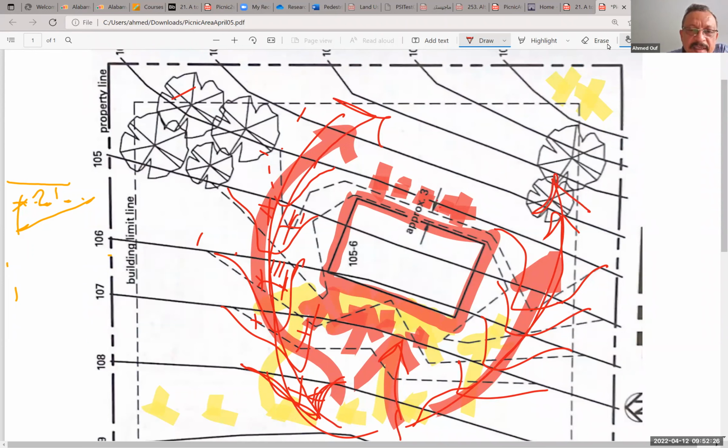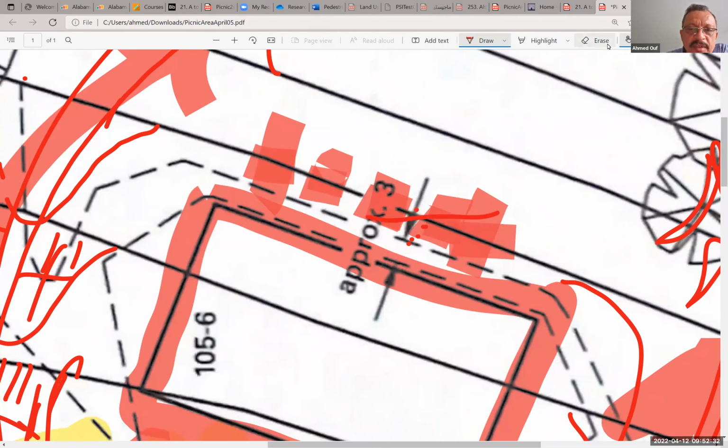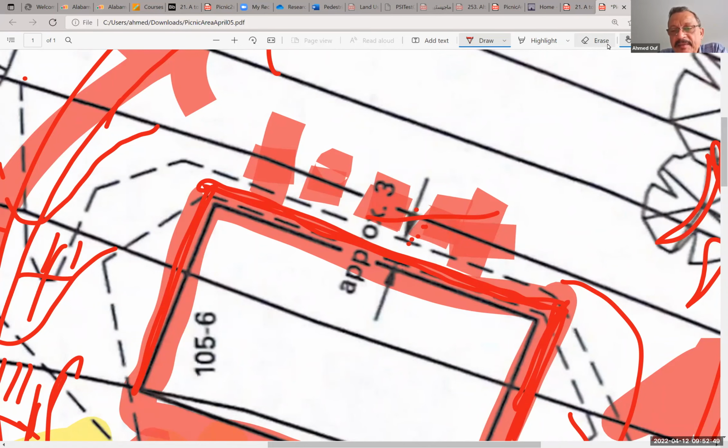And here, I'm really interested in this area. I will just make it a little bit larger here. In this area, we have this pavilion, this picnic pavilion pad, which is cement. And as we said last time, it cannot actually be sloped, or it will be uncomfortable for people to sit. So what we said is 1/4 of an inch in every foot.